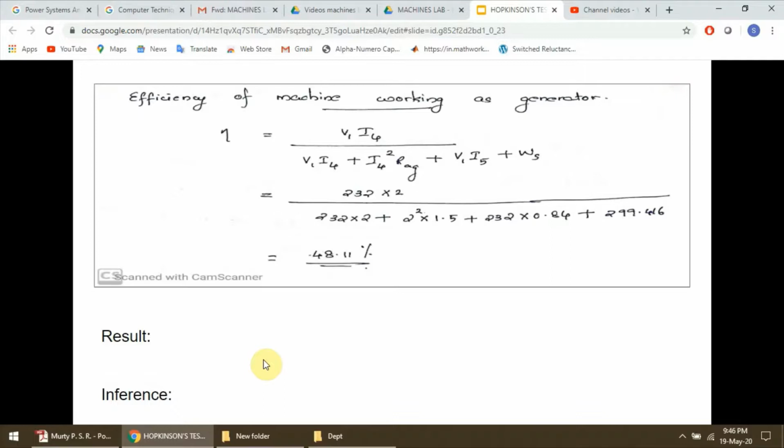But here, since both machines operate under full load condition, both the armature reaction as well as the temperature rise can be included in the analysis. That is the reason why the stray losses, or the no load rotational losses, we get will be much more accurate than what we get under Swinburne's test or any other test.